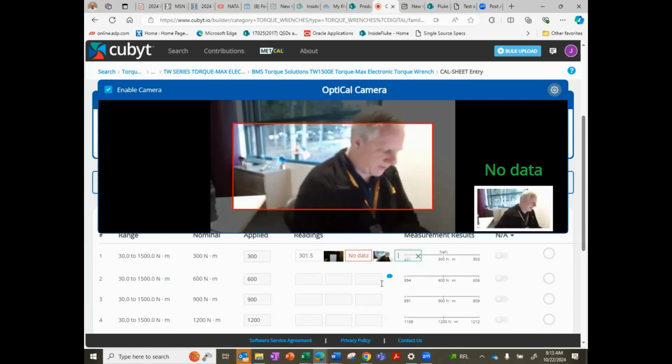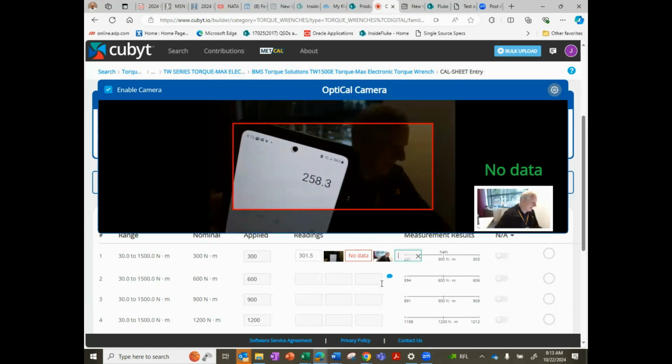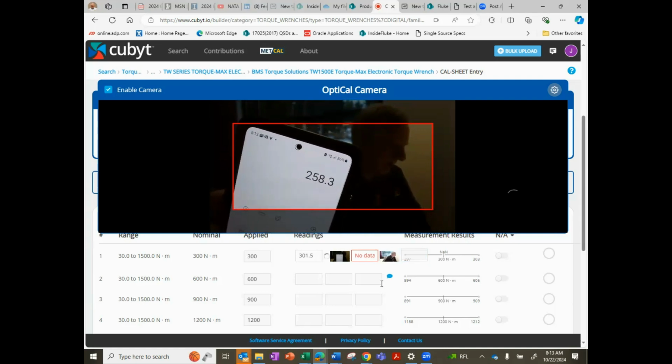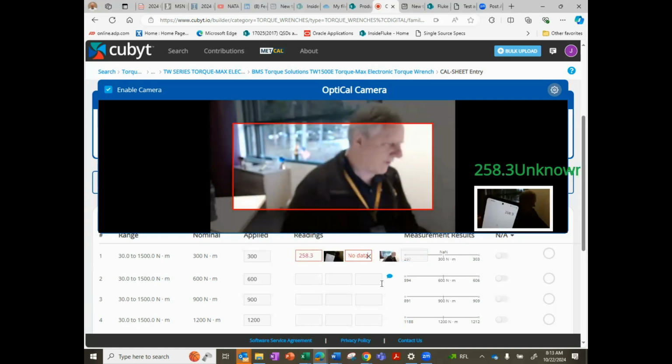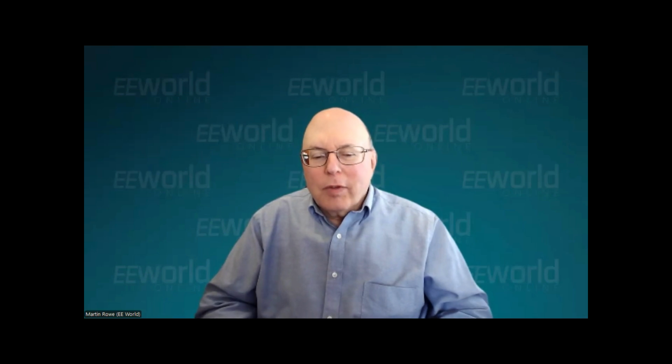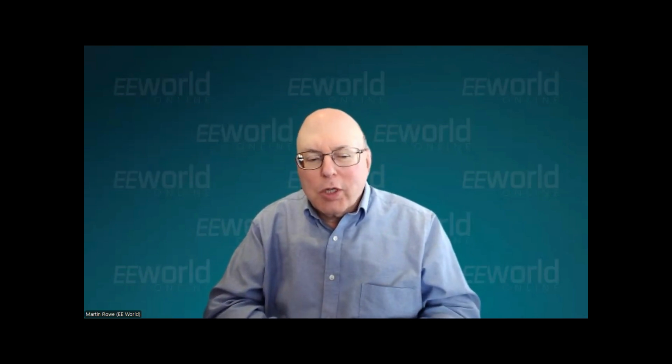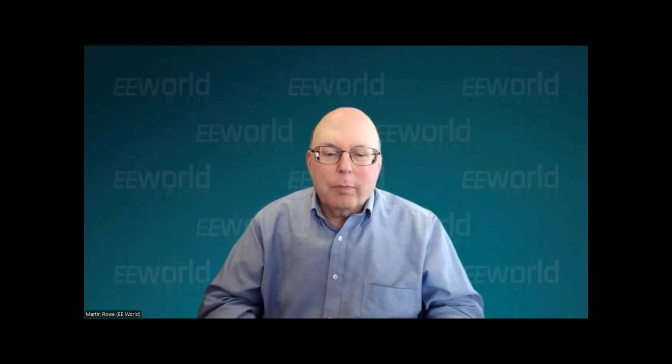And if I want to make it fail, let's make it 258.3. You can even see I'm going to be crooked and off screen, and we get 258.3. So now that you have this data, you usually need to produce a calibration report. What happens from there? Does MetCal pick it up and take it from there? How does that work? Exactly. Now that it's in data form, we can pull it into any calibration report format that we want. We can produce a certificate in Qubit itself, or we could port it over to MetCal and record all this history as a part of the calibration record.